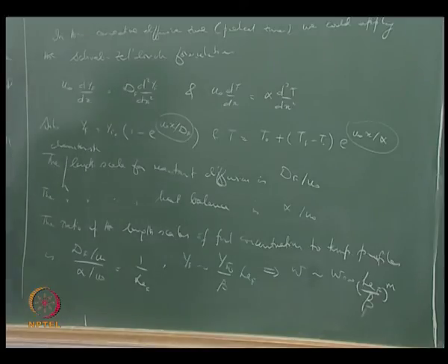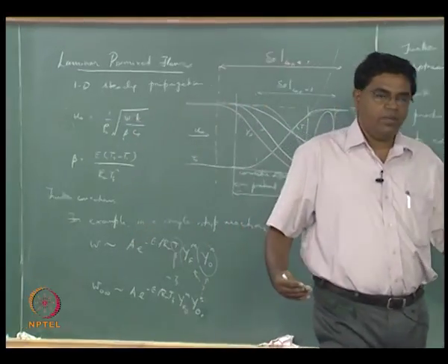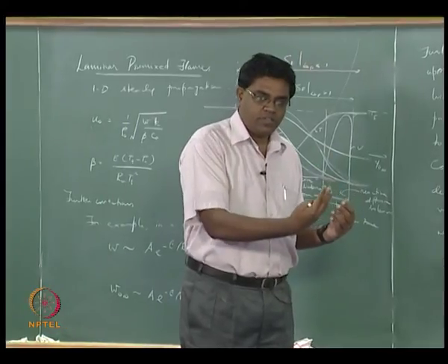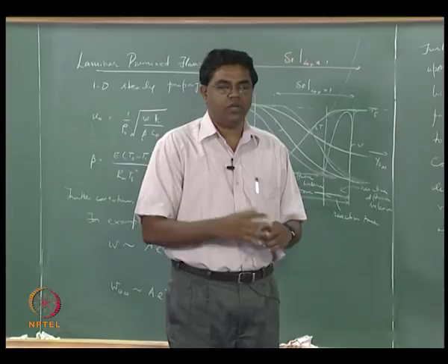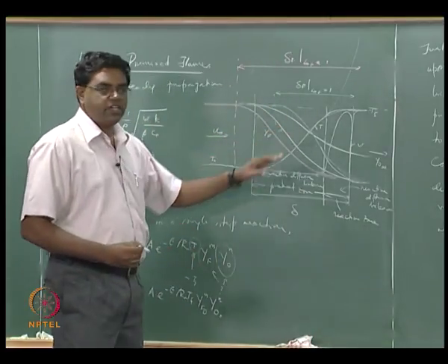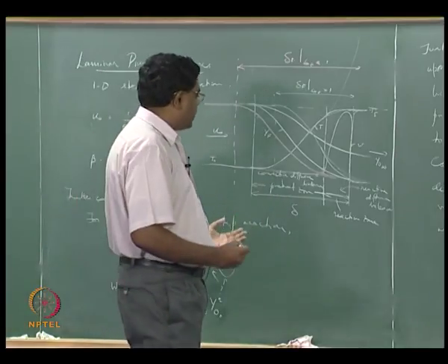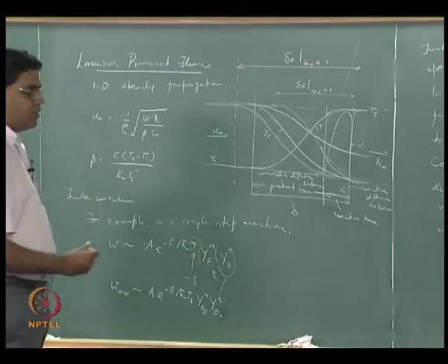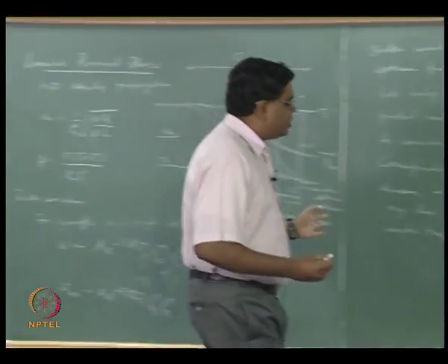So this is what we could actually plug in back here to now not only take into account upstream diffusion of products and correspondingly downstream diffusion of reactants in addition to downstream convection of the reactants, so that the concentrations of the reactants are actually coming down in the reaction zone. We could also now look for preferential diffusion. That means when you have a non-unity Lewis number, the reactants actually diffuse preferentially depending upon their Lewis number relative to the thermal balance. And then we find that the concentrations of the deficient reactant, which is more critical in the reaction zone, can vary with the Lewis number itself in a way that we can see. So this is amazing in my opinion, because we just think about what's going on and then start expecting how these variations should be.